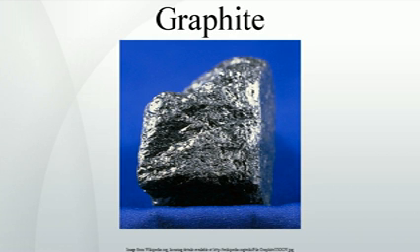Since much of the lost capacity was for carbon magnesite brick, graphite consumption within refractories moved towards alumina graphite shapes in monolithics, and away from the brick. The major source of carbon magnesite brick is now imports from China. Almost all of the above refractories are used to make steel and account for 75% of refractory consumption. The rest is used by a variety of industries, such as cement.